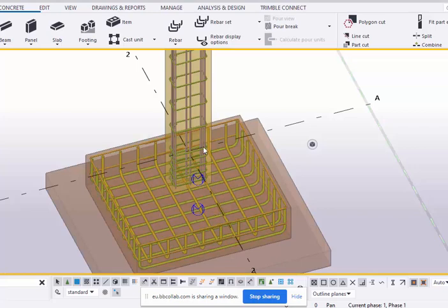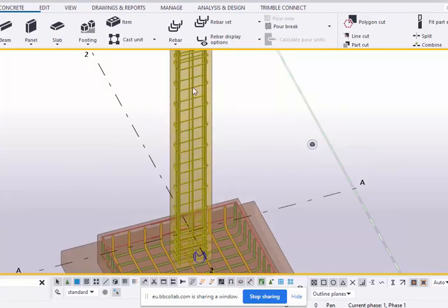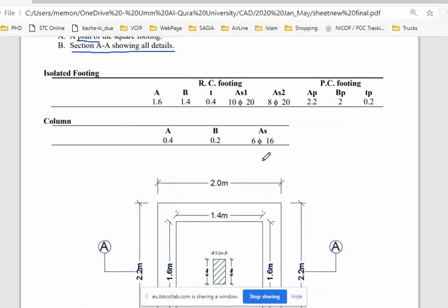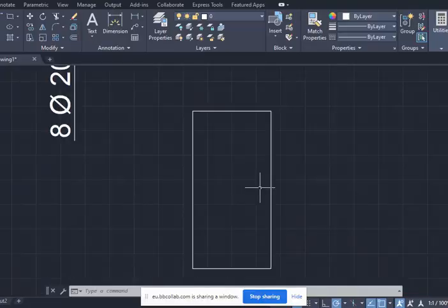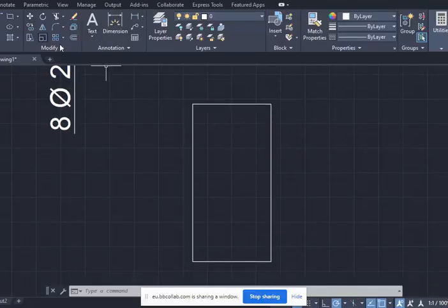Okay, now we want to put this steel over here. This is steel, we'll learn how it can be done in the AutoCAD. We can see this one says 6 dia 6 bars, so inside we have to put the 6 bars. So we can go to the AutoCAD. Now we have to put the 6 dia bars. So just offset maybe 20.